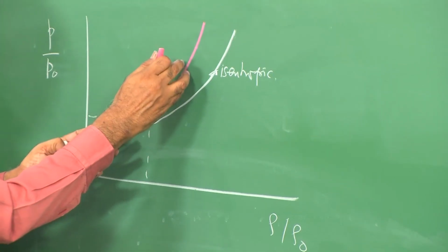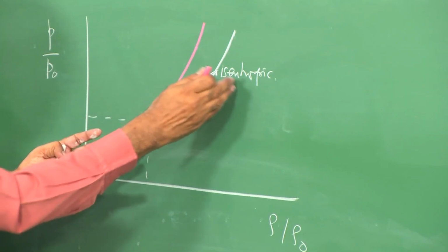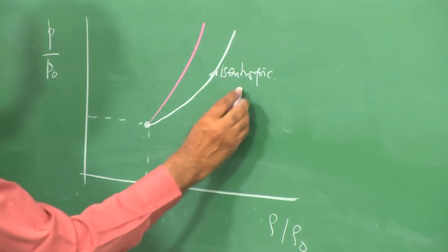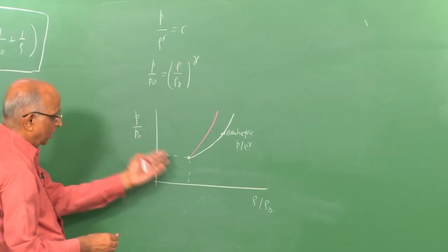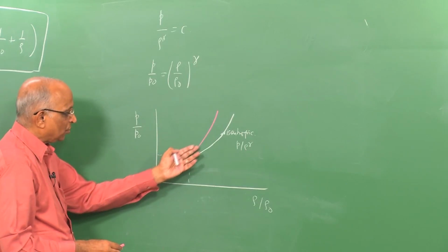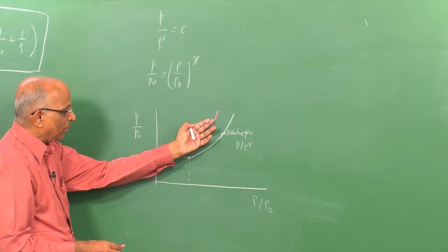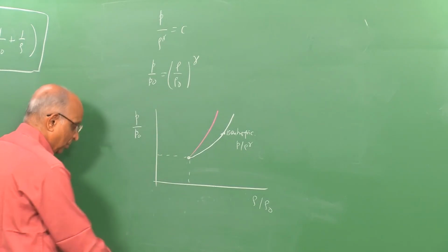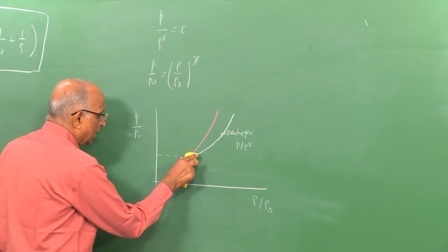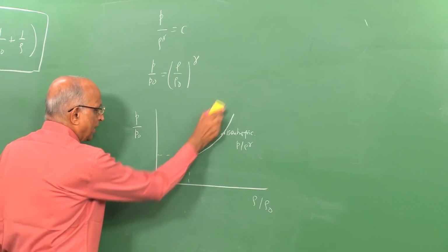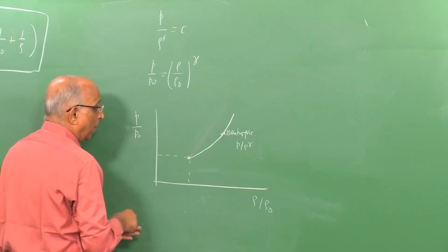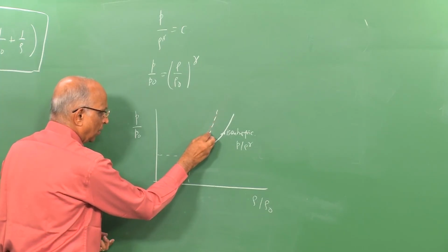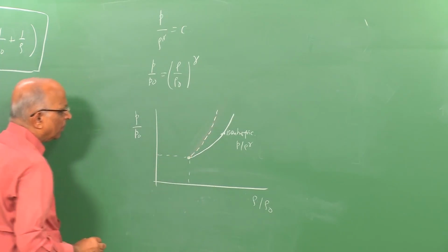Therefore I get a higher pressure ratio compared to the isentropic assumption of P by rho to the power gamma being a constant. On the state properties, I cannot show this by a continuous line, because it is not reversible, so normally we show it by a dashed line, and we say the shock properties are denoted by this dotted line across a shock.